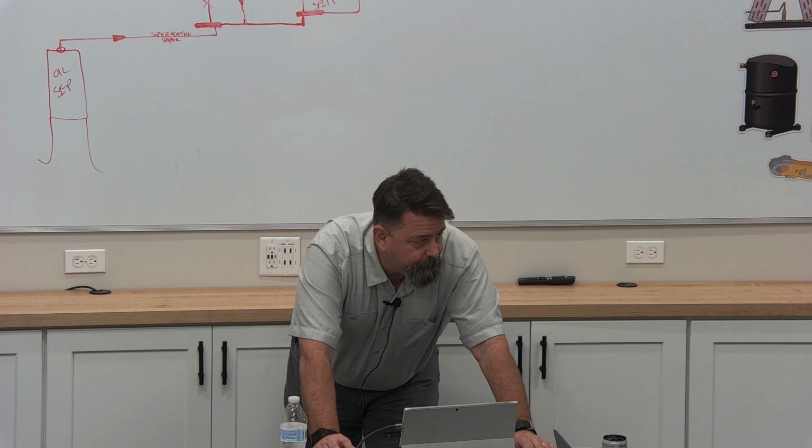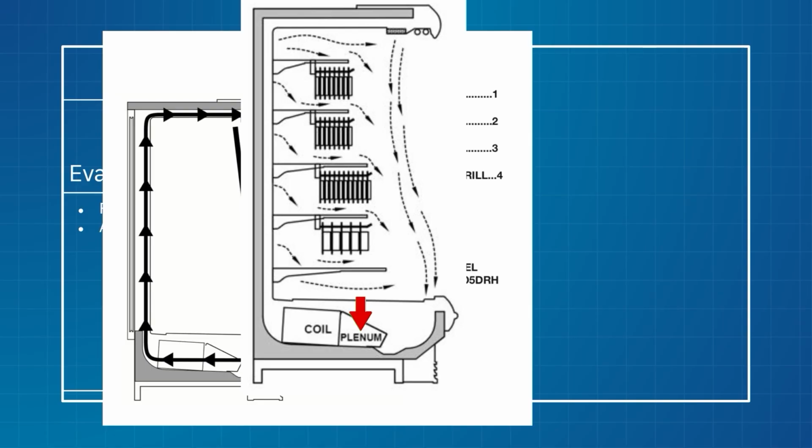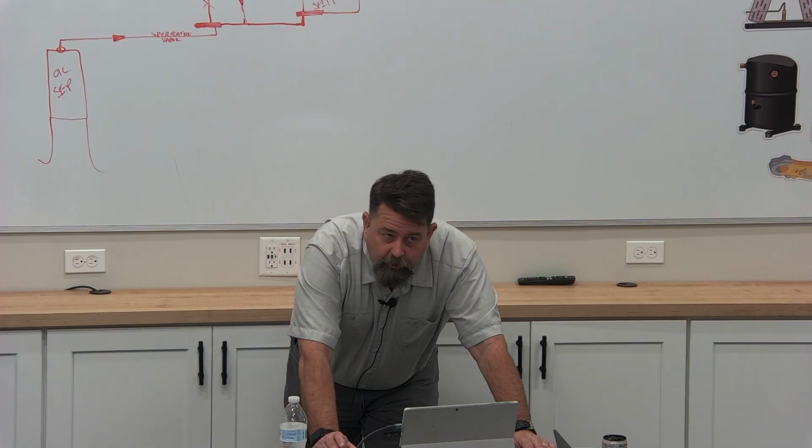There's no way it won't. Okay? So that's really important. The other thing I want to talk about, this shows this plenum sitting on the bottom of this case. That has to be sealed. All right? If it's not, when I'm trying to suck in my air here, I'm going to blow it back out. I'm going to recirculate air here. I'm going to be short air velocity. All right? So startup guys, this is big.